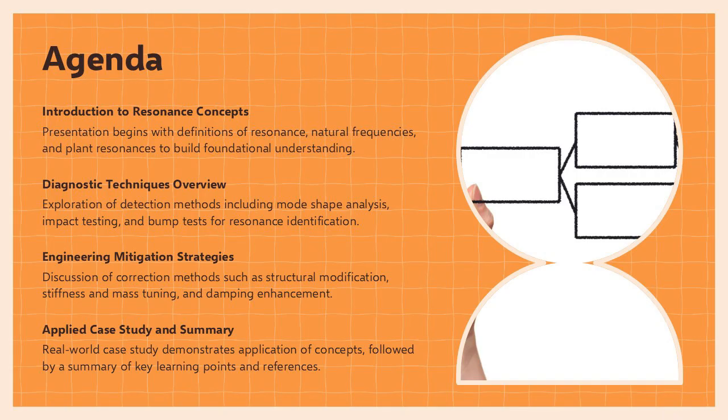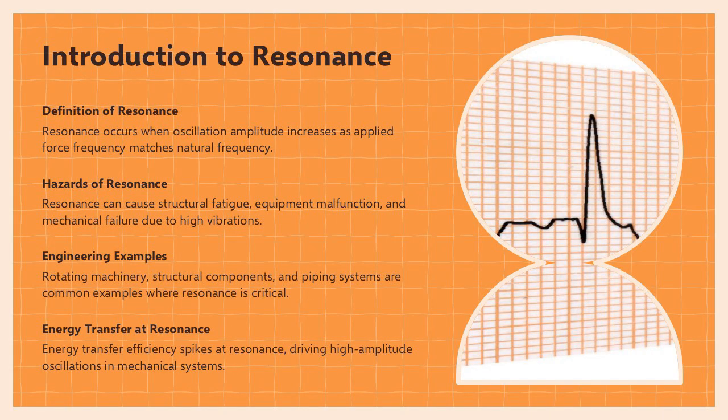Resonance is a phenomenon observed in mechanical systems where the amplitude of oscillation significantly increases when the frequency of an applied force aligns with the system's natural frequency. This introduces a potentially hazardous condition, as even small external forces may produce large vibratory responses if resonance is triggered. Engineers must understand the physical mechanisms behind resonance to prevent structural fatigue, equipment malfunction, or catastrophic mechanical failure.